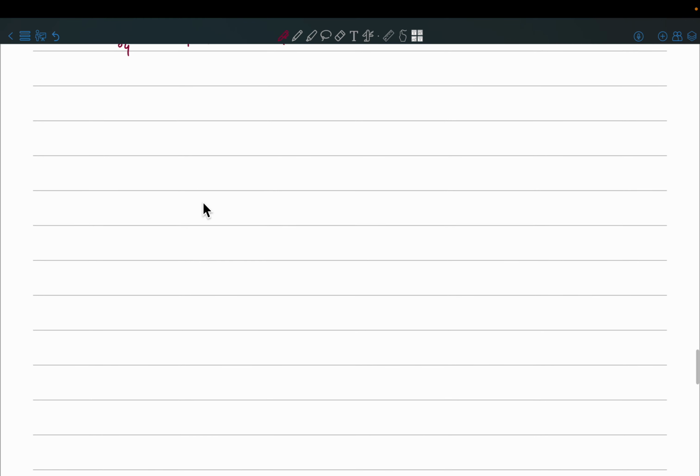So what is critical nozzle pressure ratio defined as? Do you know the definition? No? Okay, so nozzle pressure ratio is defined as P naught 4 by Pa. So this is nothing but the stagnation pressure. So remember that in a nozzle, there is no moving part, right?